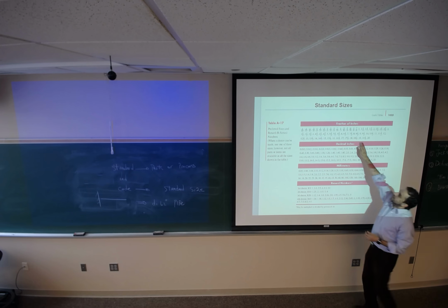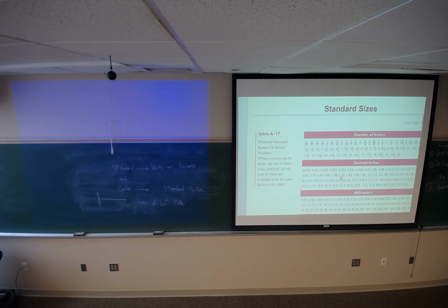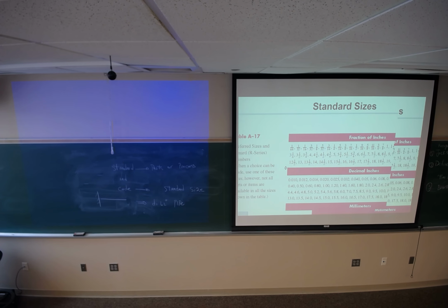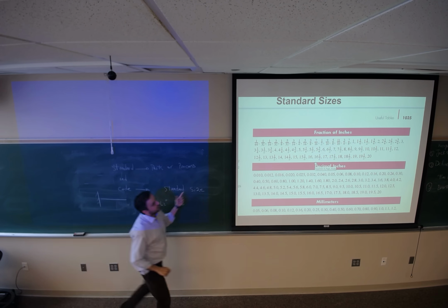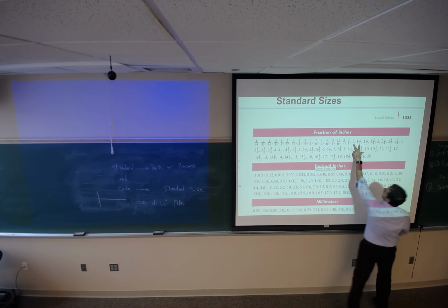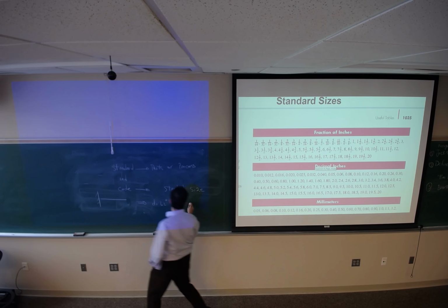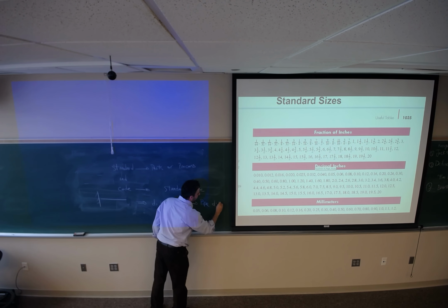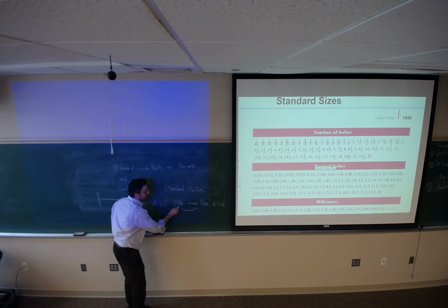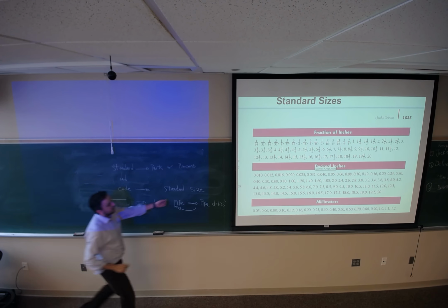As you see, the size that you are looking for is 1.2 inch. But the standard size that we have in the market is 1 inch, and the next one is 1.25. So it's much less expensive to go with a pipe with a diameter of 1.25 inch rather than ordering this size for the pipe. So by using the standard size, we can reduce the cost.